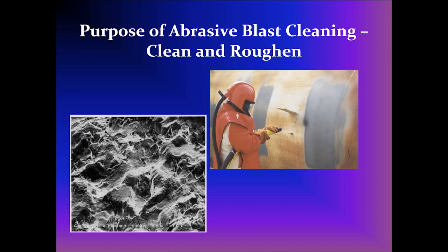So the purpose of blast cleaning, to clean and roughen. In the bottom left, you see a microscopic view of a roughened surface from blast cleaning. It looks like sort of the waves or ripples in an ocean as compared to a calm sea, which would be a smooth surface with no abrasive profile on it.